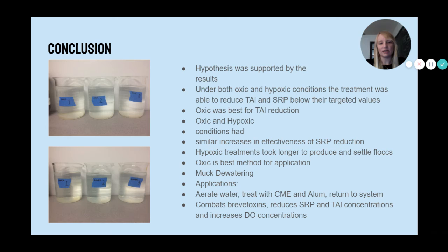One notable observation that occurred throughout the experimentation was the increase in floc settlement time the hypoxic trials experienced. The oxic and control trials were able to see floc production and settlement within 10 to 20 minutes of addition of the mixture. However, it took upwards of 45 to 60 minutes for the treatment to produce and settle the floc under the hypoxic conditions.